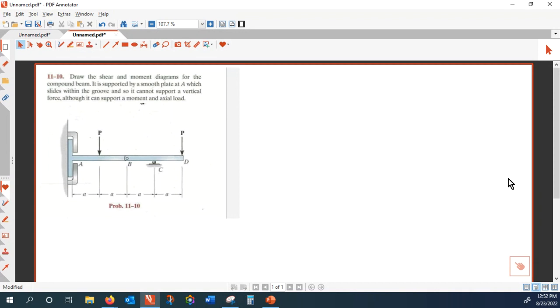So basically, A is only offering resistance toward what? Rotation. So it only develops bending moment. It resists against the rotation. Can you see that? Yeah? All of this was to understand how to make the free body diagram after releasing that. So you release A, and you realize that AX is irrelevant, AY is 0, and MA is something you have to include in your free body diagram.